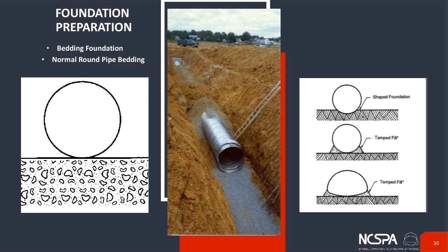With flat bedding, which is pretty typical for factory-made round pipe, the pipe will be placed directly onto the fine-graded upper portion of the foundation. And then the soil is compacted underneath the haunches of the structure in the first stages of backfill. We refer to the haunches as basically the area from halfway up the pipe down. So the upper 2 to 6 inch layers of your foundation should be pretty loose. That allows your corrugations to seat into the bedding.